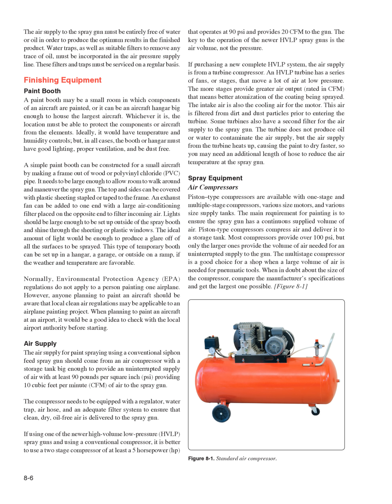The main requirement for painting is to ensure the spray gun has a continuous supplied volume of air. Piston-type compressors compress air and deliver it to a storage tank. Most compressors provide over 100 pounds per square inch, but only the larger ones provide the volume of air needed for an uninterrupted supply to the gun. The multi-stage compressor is a good choice for a shop when a large volume of air is needed for pneumatic tools. When in doubt about the size of the compressor, compare the manufacturer's specifications and get the largest one possible.